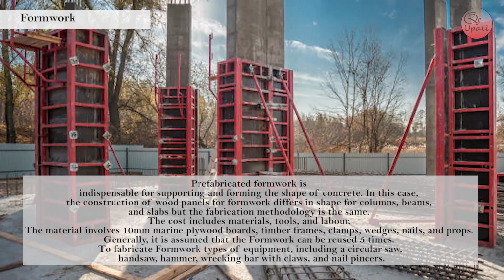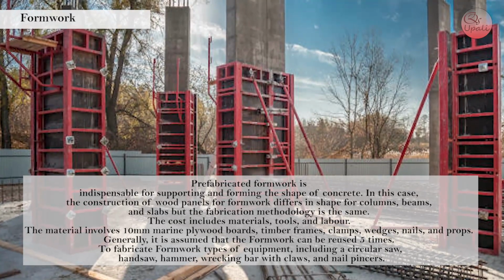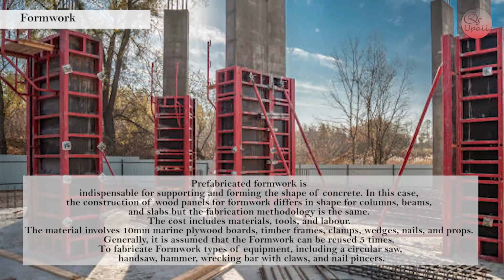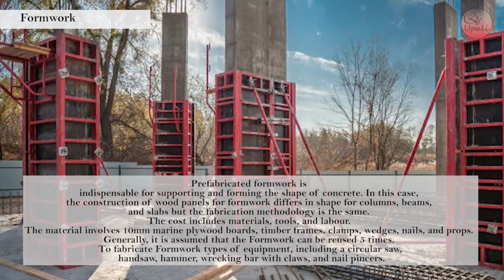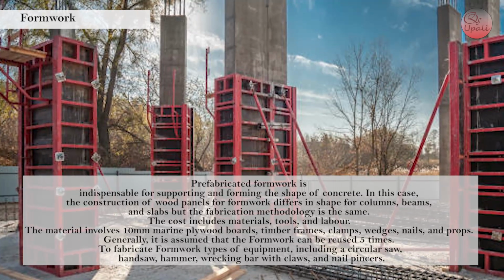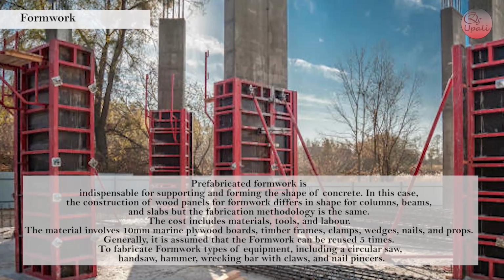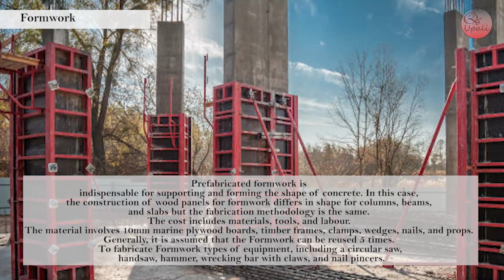Formwork. Prefabricated formwork is indispensable for supporting and forming the shape of concrete. In this case, the construction of wood panels for formwork differs in shape for columns, beams and slabs, but the fabrication methodology is the same. The cost includes materials, tools and labor.